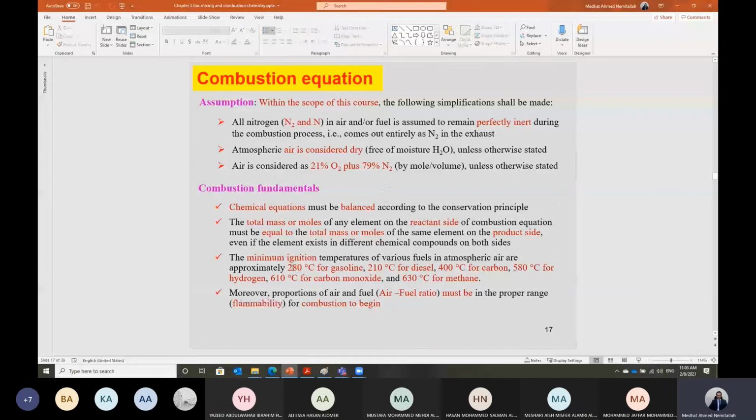Even with a spark? The spark itself is a combustion source; in this case we have high temperature. So usually when we do numerical modeling, in order to start ignition in the numerical calculation, we have to create a zone of high temperature, higher than the self-ignition temperature. We have to initialize the calculation from a higher temperature so that the model can understand that there is ignition. So the ignition source should be at a higher temperature than this value. Okay? Still have a question, Mustafa?